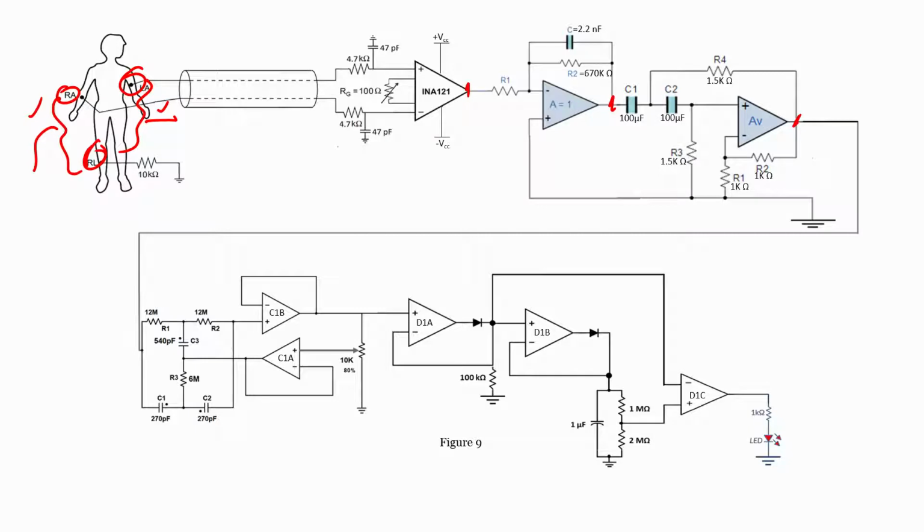That is the reason we require a higher CMRR operational amplifier, and since we have to take the difference between the 2 voltage sources, we require some difference between the outputs. So in order to perform the difference, either we go with a differential amplifier or with an instrumentation amplifier.